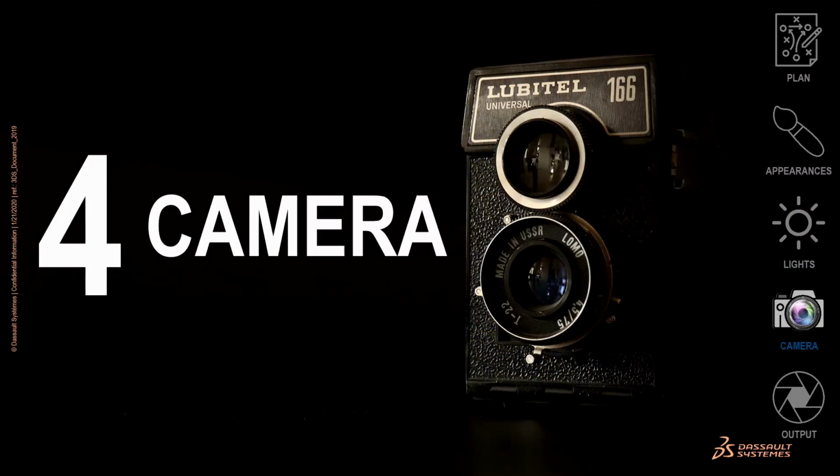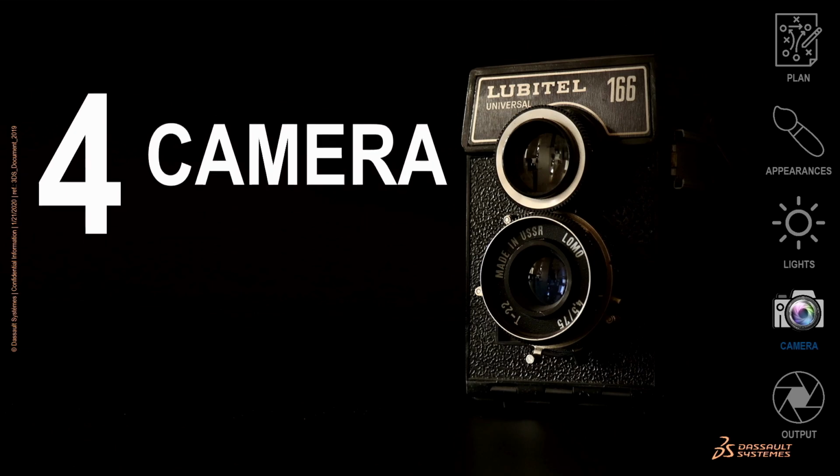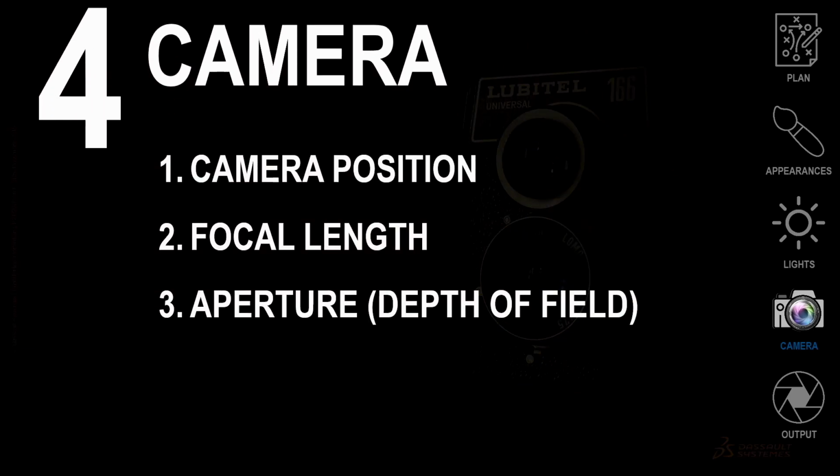Okay, cameras. This is another one that gets very confusing. Most people who are using Visualize are not photographers. So what I want to do is kind of run through what some of the critical camera settings are, because there are a lot in there. So we'll break this down into really 3 important pieces of information as far as what a camera does for us. So where the camera is, its actual position, its focal length, and its aperture settings.